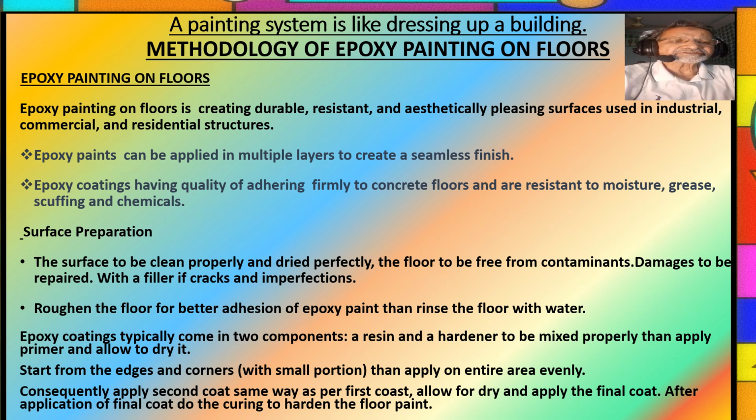Ensure the area is well ventilated. Test the surface. If you are unsure about the condition of the floor, for example whether it is too porous or uneven, test the epoxy on a small section first to ensure it adheres properly.